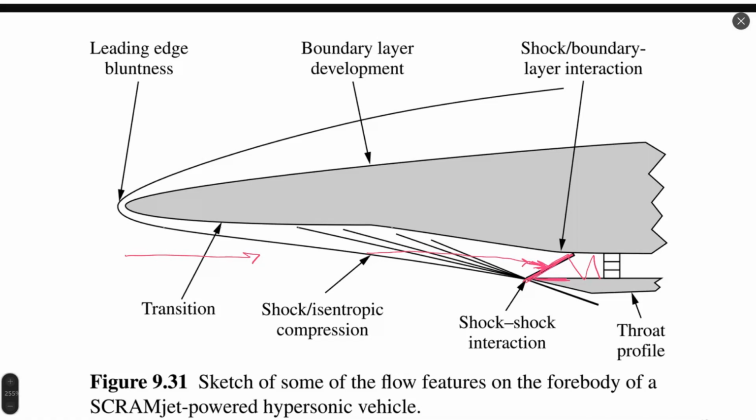Losses happen, of course, but not because of the shape or number of shock waves, of which there is theoretically an infinite number. On each shock wave we have infinitesimally small losses, but these losses happen mostly because of friction of the flow with the wall.